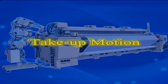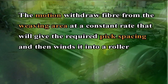Coming to the take up motion, the motion withdraws fabric from the weaving area at a constant rate that will give the required pick spacing and then winds it onto a roller. Modern silk looms are built with large diameter take up rollers which provide sufficient surface contact to resist slippage under normal conditions.